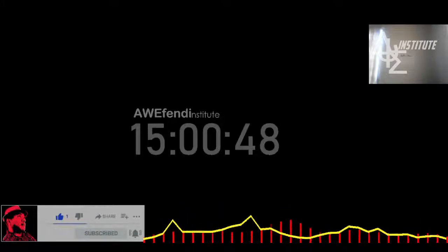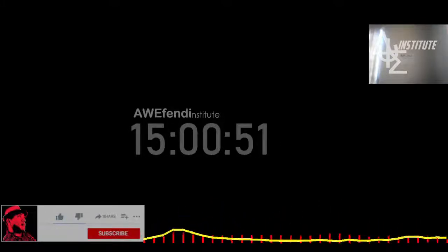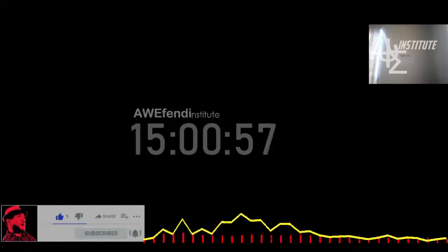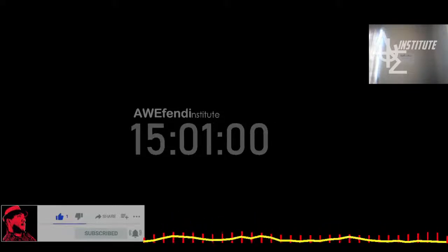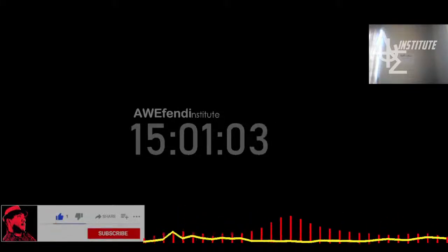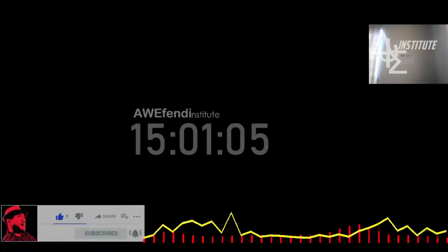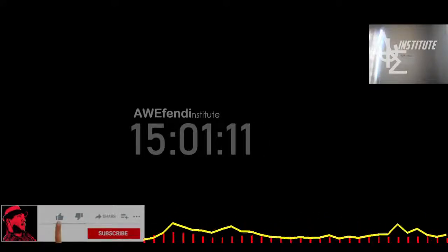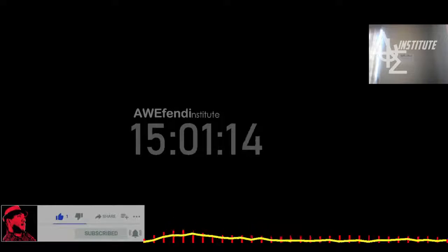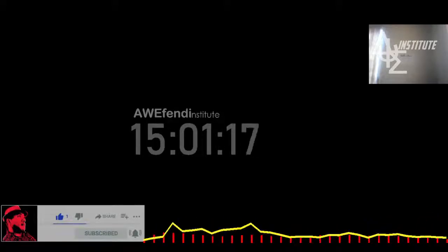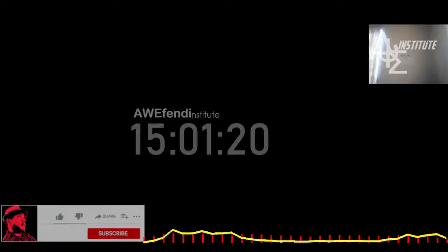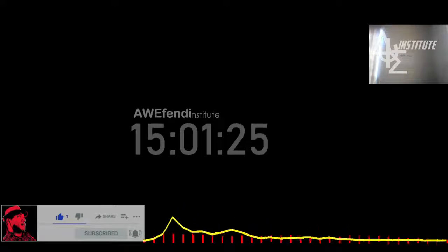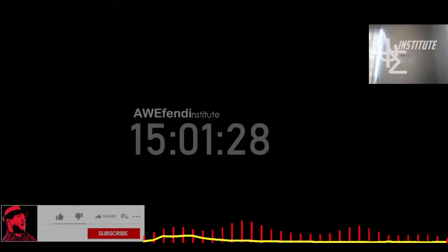The first one's the simple mixer T demo. I'm going to show you some basic steps for geometry prep for fluid flow, so extracting a fluid volume, for example, from solids, setting up your boundary conditions and running the calculation. Then we're going to have a look at some monitors, do a quick analytical check that everything is indeed okay. And then I'll show you how to parameterize some boundary conditions. I think my colleague Madhu before was showing how to parameterize geometries. Here you can also parameterize boundary conditions.